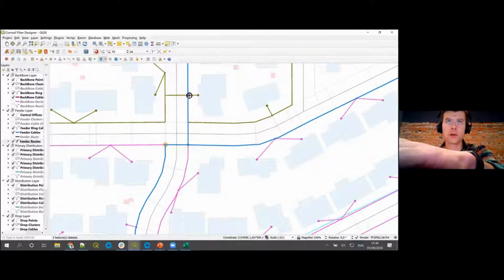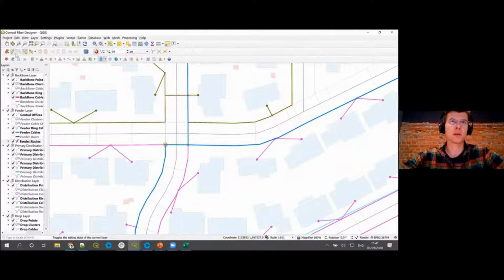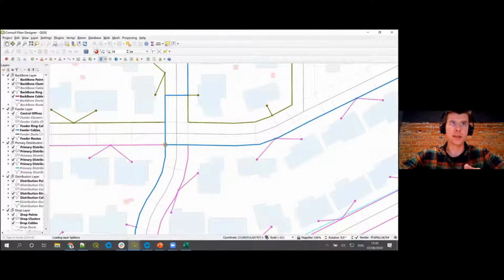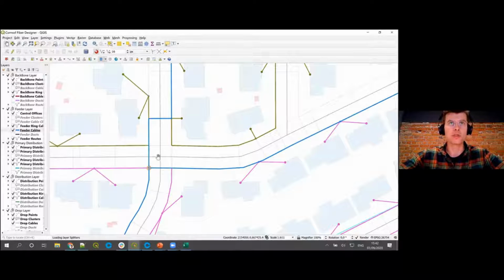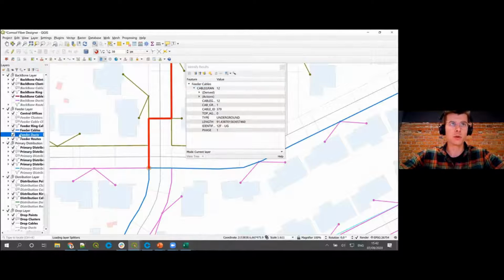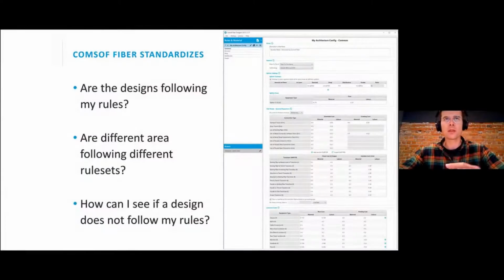So we just delete part of the route, add a new piece, save that, and then we recalculate the network design. Now, calculation has finished, and what we see is that this change of route that we have drawn is now used for routing the cables. So, and not only the cable is rerouted, we have our new cable here, but also the duct where it is in will be rerouted, and the bill of material will be adjusted. The goal is to come up with a cost-effective design which is buildable.